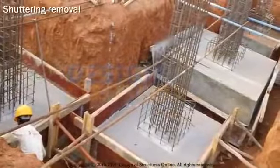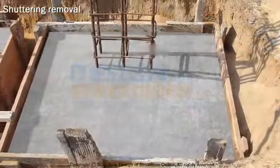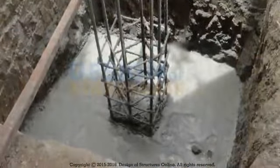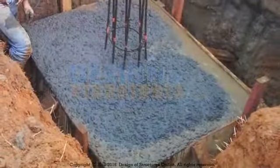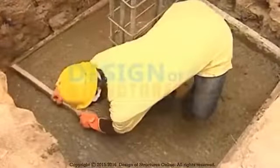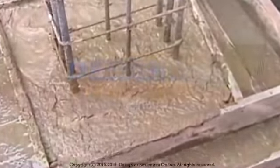Shuttering removal. The formwork removal procedure should be supervised by the engineer to ensure the quality of hardened concrete in structural members. That is, it should be free from or have minimum casting defects such as honeycombing, size and shape defects, etc. These defects in concrete influence the strength and stability of the structure, thus immediate repair works can be done or the members can be rejected.